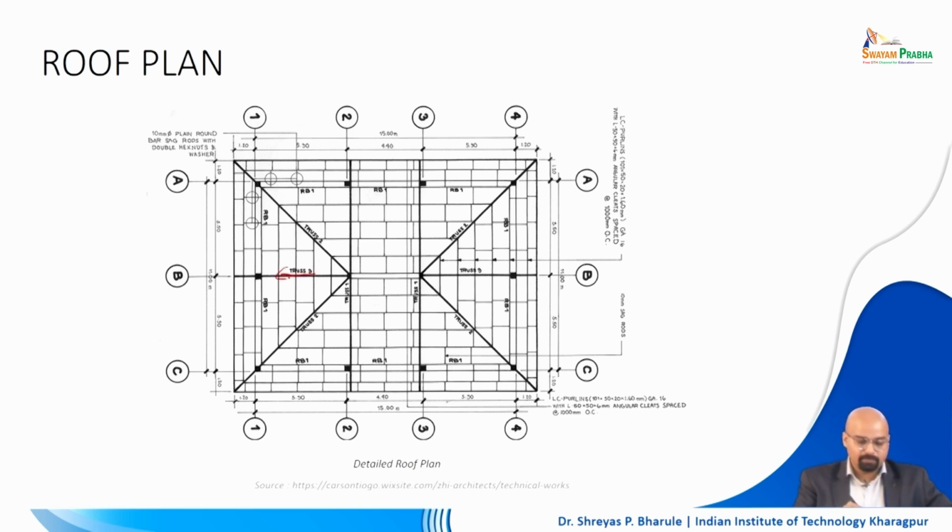So, you have four ways in which this roof steeps down, but to do this you will require three different types of trusses, truss one, truss two and truss number 3, right, because the span keeps on changing from this point to this point to this point, and it is supported at 1, 2, 3, 4 locations, right, and it extends further to create an eave, right.